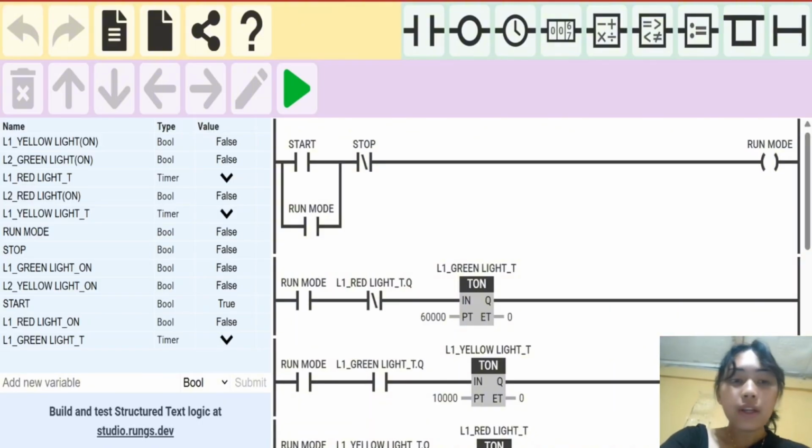A potential failure in our system is a logic error that could activate both lanes simultaneously. The PLC prevents this by using interlocks that block one lane when the other is active. If the system needs to scale, such as adding more lanes, additional inputs, outputs, timers, and ladder rungs would be required. The same alternating logic can still be applied.